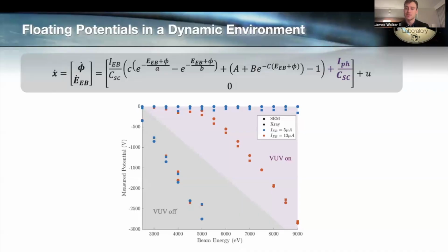So what this actually tells us is that in order for our control to still hold, our electron beam current has to be greater than whatever constant positive bias the spacecraft is experiencing. And we see that once we increase the current to 13 microamps, charging occurs at about 5,000 volts, and then once it occurs, we get that nice linear relationship that we would expect.